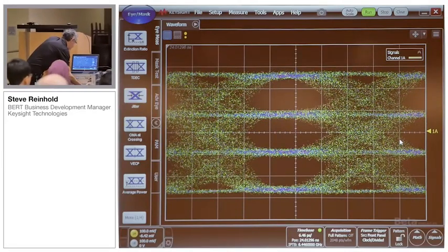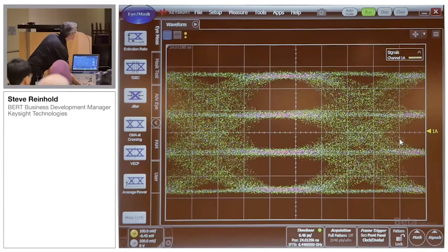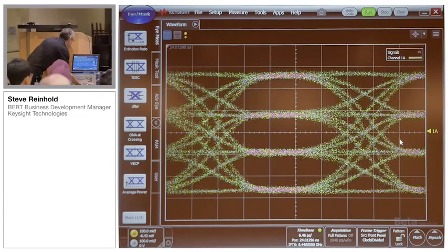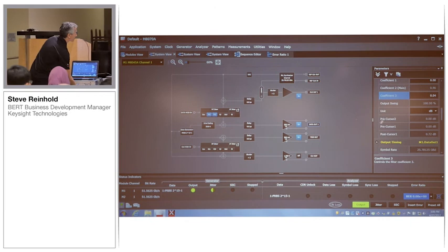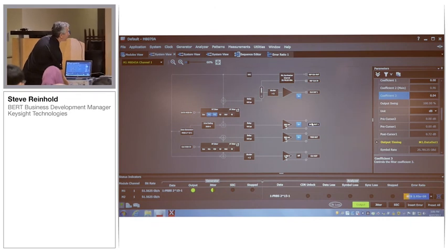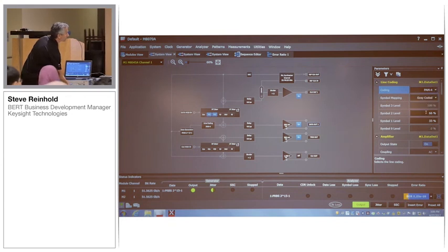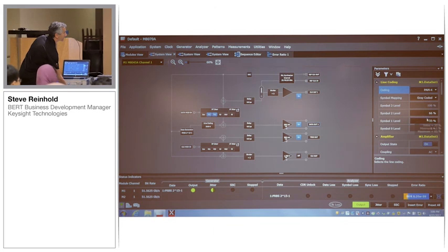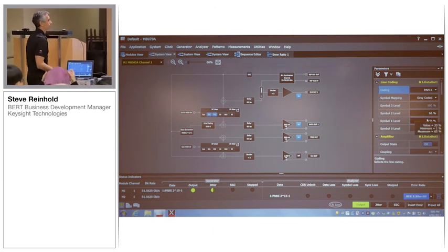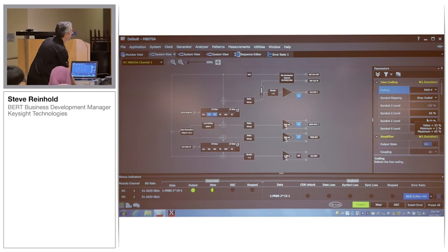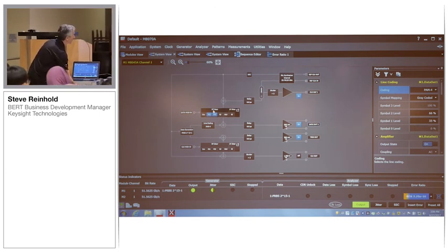So let me flip over to the GUI, and turn the jitters off so I don't confuse myself. All right, so the controls that I was just manipulating were the data output controls. If I scroll up here, you'll see the things that I was doing. PAM4 NRZ is as simple as that. The linearity controls, we have 0, 33, 66, and 100. I just incremented that to show you the linearity test.